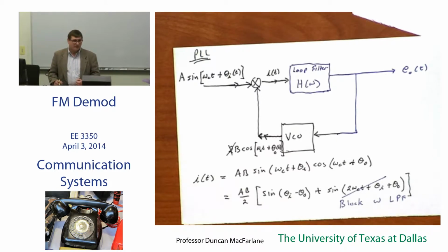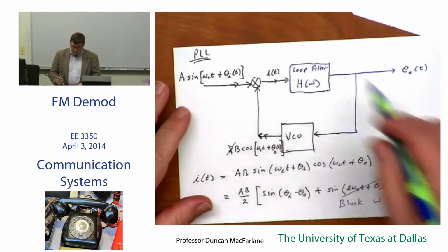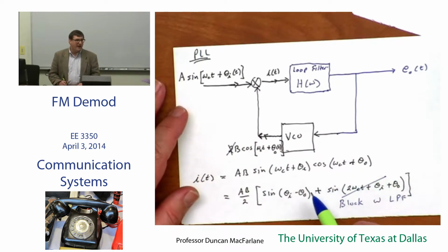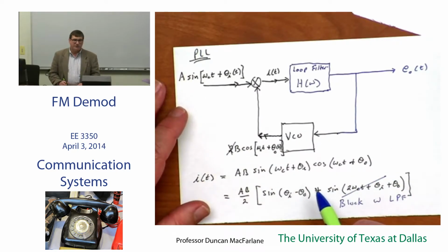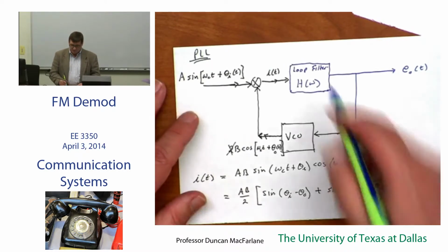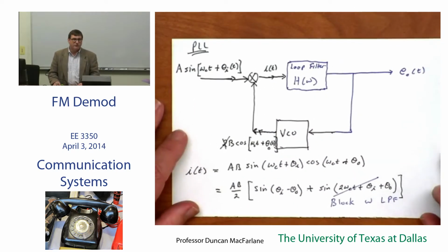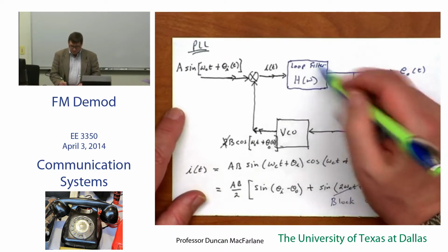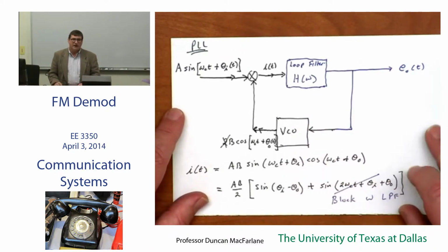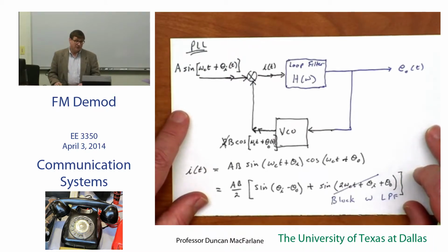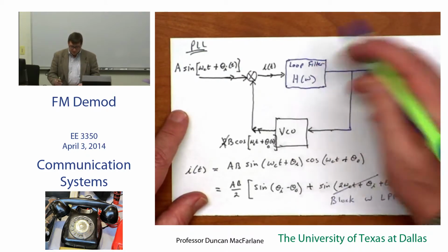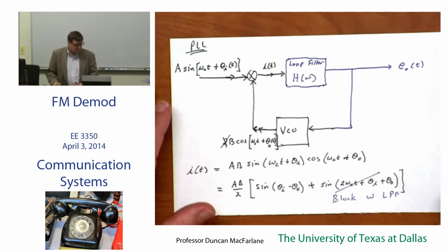Okay. If it's too fast, then I may not do a good enough job of discriminating that, or worse yet, I may have some instabilities that creep into my system. So there's a balance, and generally, if you want a rule of thumb, I don't know if you'll ever use this, you should never go higher than a second order analog filter for that, and that's very limiting on the shape and the scale of that. Okay, especially if this happens to be an active filter.